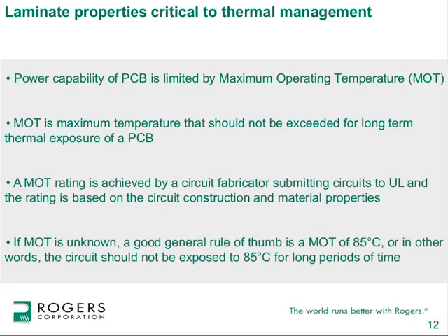And if you're running models, which I do a fair amount, and you really don't know what the MOT of a circuit is, a good rule of thumb is to use 85 degrees C. So if you're comparing different models and looking at thermal models, and you just don't know what the MOT of a circuit is, just assume 85 C is the highest temperature that circuit should achieve.